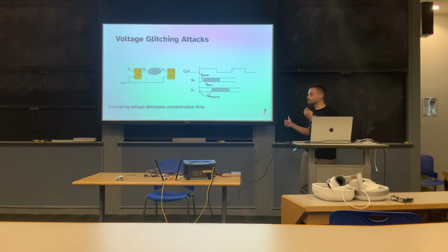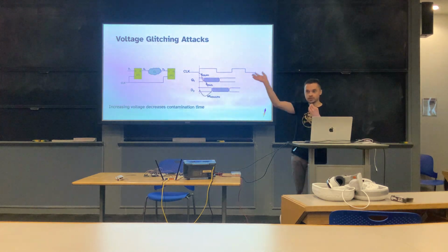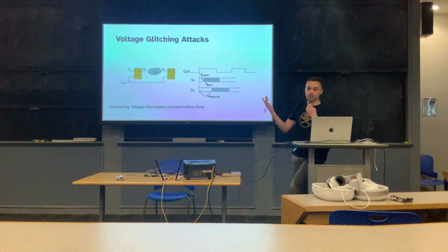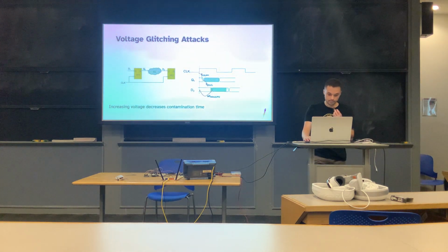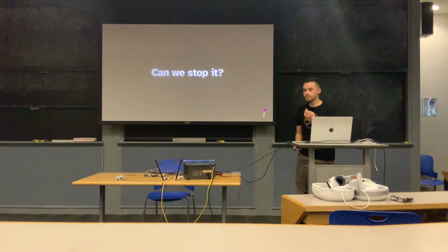Any questions? So we hit this metastability, and then what just happened in the Arduino, we had metastability throughout the whole chip. Clearly that meant the serial ports gave us some weird data, but it also broke the loop. So we were able to break out of the loop and see the flag. Yeah, so it brings it forward, we break hold time.